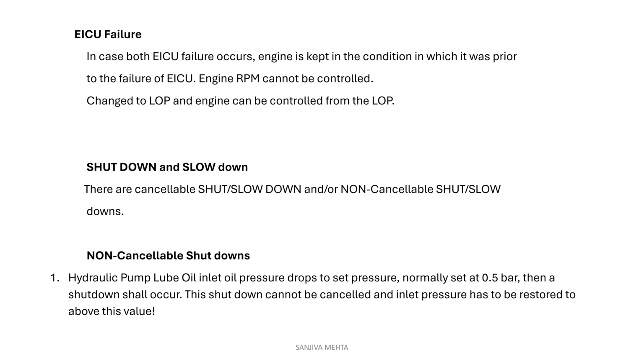Hydraulic pump lube oil inlet oil pressure drops to some minimum set pressure. Okay. Inlet pressure is normally set at 0.5 bar. Then a shutdown shall occur, because no oil is coming to the suction.